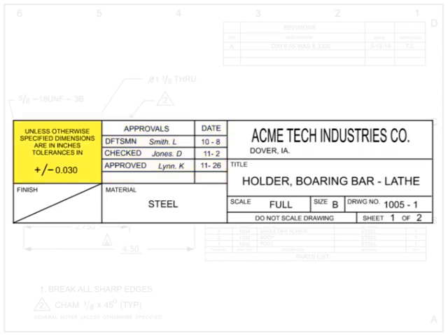Tolerances are defined as the difference between the lowest and highest acceptable limits of a dimension. It is almost impossible to machine parts to the exact dimension called out on the drawing. Tolerances allow a machinist to deviate within a specified limit that will not adversely affect the final part. The tolerances block contains the default tolerances for dimensional callouts where no tolerance is otherwise noted on the drawing. The tolerances in this block should be followed unless specifically marked otherwise. Examples of tolerances are plus or minus 0.030 or plus 1/64 of an inch.